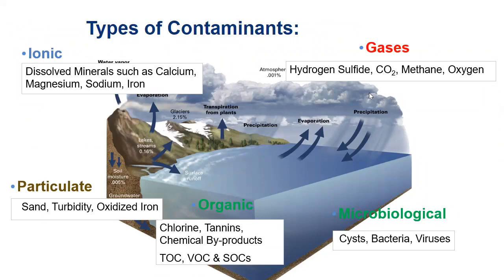Hydrogen sulfide is the rotten egg smell that can come from rotting organic matter or from gas deposits or breakdown of sulfate containing rocks from the acid rain. Maybe part of how we get sulfides or sulfates into the water supply. And then there's dissolved CO2. Dissolved CO2 may be part of the natural gases in the air or the breakdown of carbonates into CO2 and gassing off. And then there's methane, which may result in wells from drilling, intersecting those sealed gas pockets while we're looking for water pockets, those sorts of things.